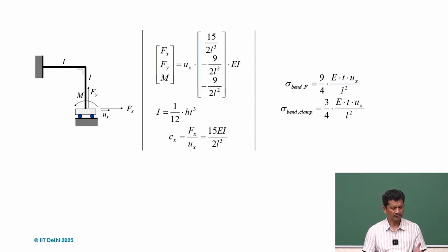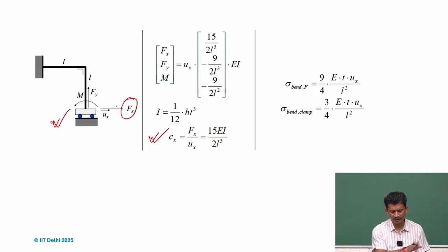So for instance, if we have this kind of thing, supported like this, what will happen? What will be the stiffness? We can find the stiffness in the x direction. What one needs to understand is what the boundary conditions imposed here are, and I think one should be very clear about that. It's not M equal to 0. M will always be there. What is 0 is, if you call it psi, the angular deformation. This is not changing. It's fixed, and that's why we have the roller.